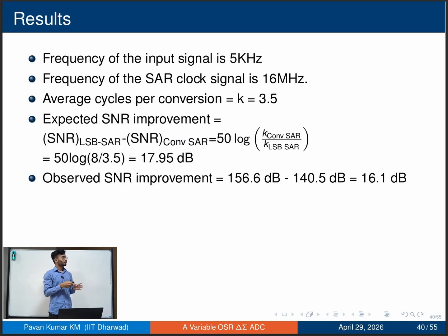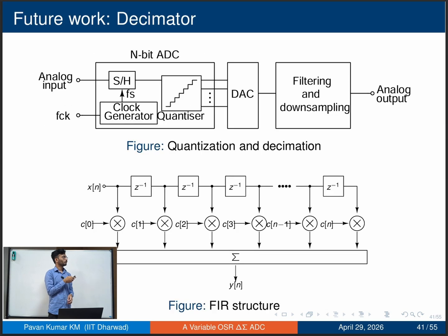Since this output needs to be reconstructed and decimated, a decimator needs to be designed. But the conventional decimator is designed for a fixed rate ADC, so we cannot use the same one for this. That will go down as one of the future works.